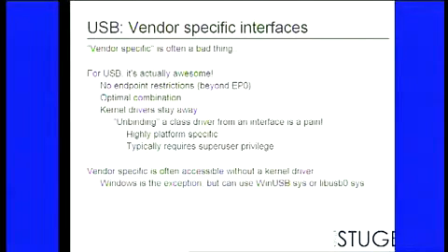So yeah, you make the optimal combination of endpoints, and maybe your device isn't really a HID, so then it's good to use vendor-specific instead. Another big benefit is that kernel drivers will not attach to a device with a vendor-specific interface, because kernel drivers are written to support one specific device class, or maybe a couple of specific device classes. And for vendor-specific, there's no way to know what the device expects and how the driver should drive it. It's vendor-specific. So there's no kernel driver to consider if you're going to write some software to program this device on your own.